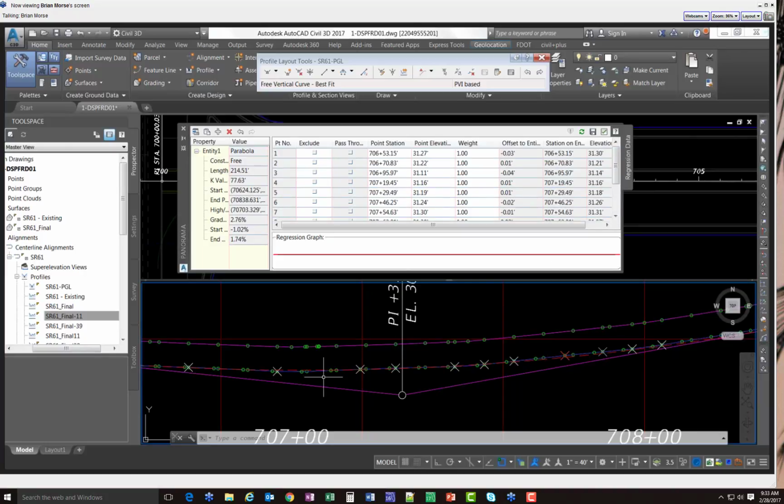And of course, because there's terrain modeling going on here, it's not always going to be perfectly smooth vertical geometry. But that's okay. It's because we're dealing with TIN triangles. So however dense the triangles are is what you're going to get for a straight line interpolation between points.